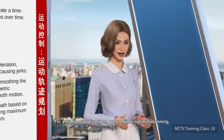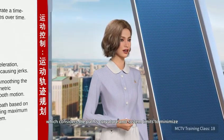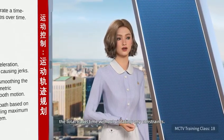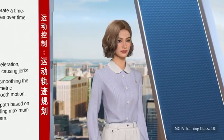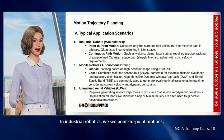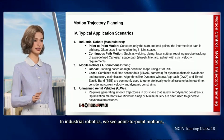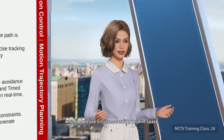For advanced applications, we use time-optimal planning, which considers the path's curvature and system limits to minimize the total travel time without violating any constraints. These planning concepts are applied across a huge range of fields. In industrial robotics, we see point-to-point motions, like pick-and-place tasks, which often use S-curve planning in joint space.